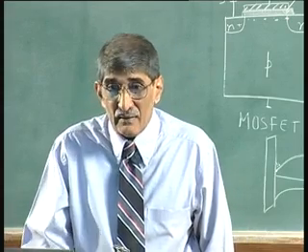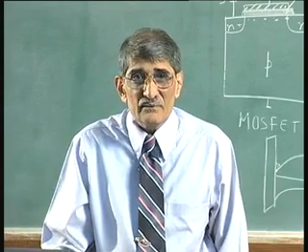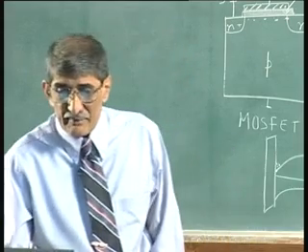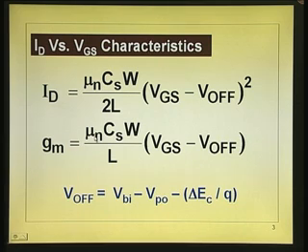Okay, now we also argued in the previous case of MESFET, when you go to higher and higher electric fields, the mobility will degrade because of field. But then you write everything in terms of the velocity, and then you can get the velocity overshoot benefits, which are very large. Just in this connection, suppose I go to very high fields, you get the velocity overshoot effect, you get the transfer of electrons from the lower valley to the upper valley.